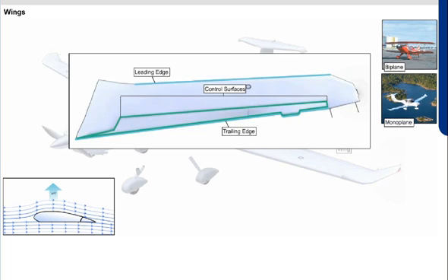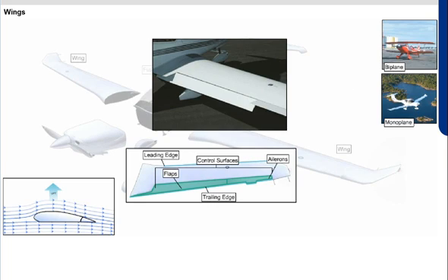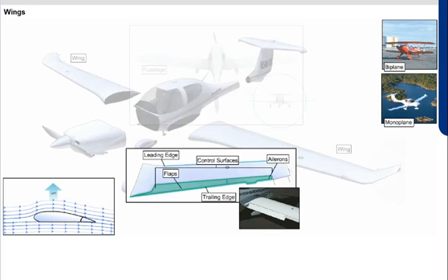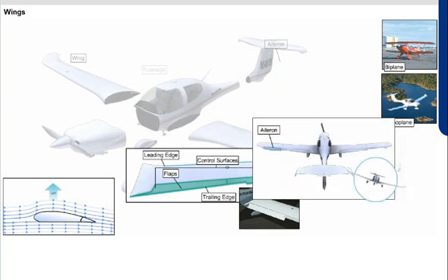Two types of control surfaces are attached to the trailing edge of each wing: the flaps and the ailerons. Flaps extend outward from the fuselage to approximately the midpoint of each wing. The flaps are normally flush with the wing's surface during cruising flight. When extending, the flaps move simultaneously downward to increase the lifting force of the wing for takeoffs and landings. Ailerons control the bank of the airplane. The ailerons are attached to the outboard trailing edge of each wing and move in the opposite direction from each other.